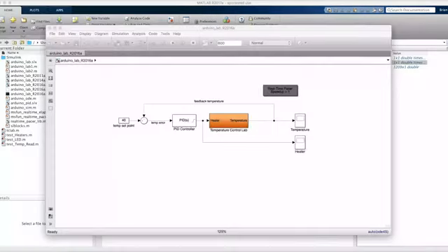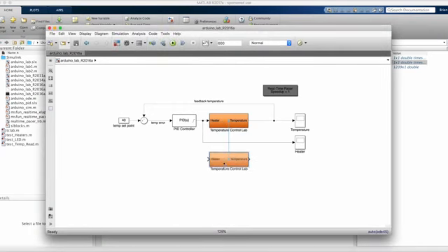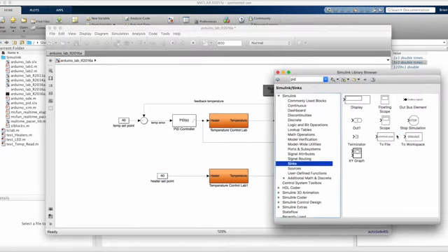Okay, at this point I could go back and tweak the PID gains and see if we can get a better controller, but it takes 10 minutes every time I run this, and this is taking a long time. Not only that, but most of the controller designs that I want to try require me to have a mathematical model of the system, which I don't have. We've done everything so far without really knowing anything about our hardware. So at this point, I want to do some system identification.